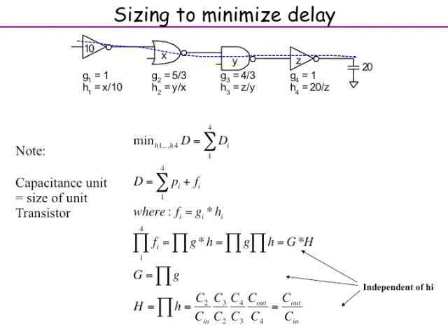Okay. Now if you see, G is a constant because that is the characteristic of the gate. So Hi is a variable, which means Fi is a variable. If I find Fi, I can find Hi, and then hence I can find XYZ. So my variable to be found is F1 till F4. That is, I want to find the optimal fan outs, which will minimize the delay.